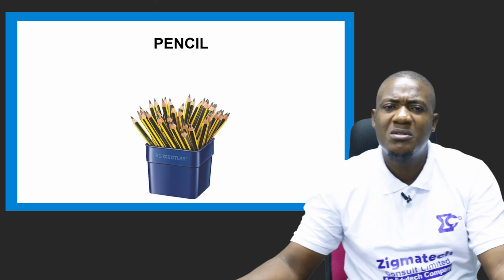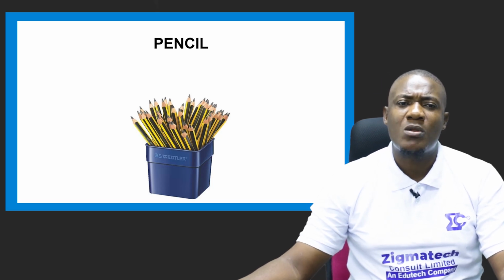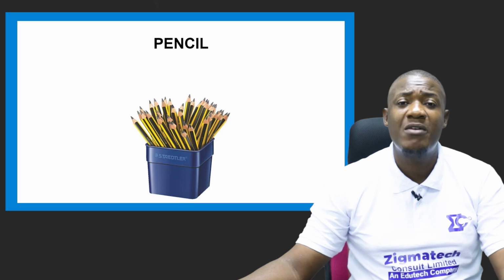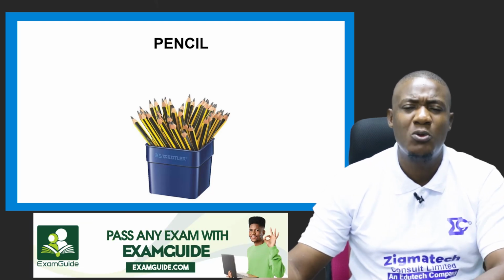We have basically two types of pencil for technical drawing. We have the B series pencil, and we have the H series pencil. But we don't make use of the B series in technical drawing. We make use of the H series in technical drawing. The H there means hard, while the B in the series means bold.